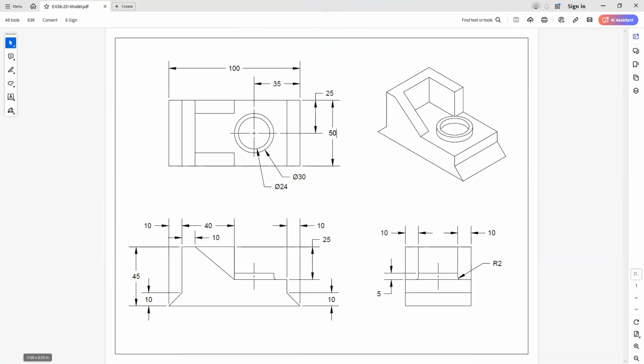All right, so once again, I do have this line that's created here. And I also have this line here at the bottom. Now keep in mind that all of these other lines here that are going across are the points where I selected for those construction lines, right? So I don't have to worry about any of these horizontal lines, as they are already created. So I got those all from the locations that were located on this drawing. What I need to do is figure out where these vertical lines are at. So remember that the total distance across here is 50. So I do know how long this top line needs to be. That's going to be 50.